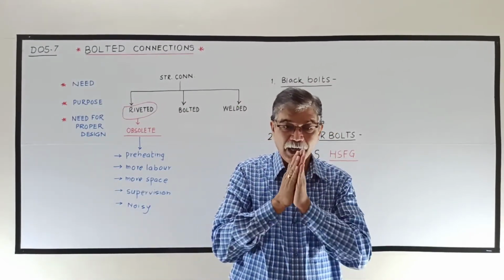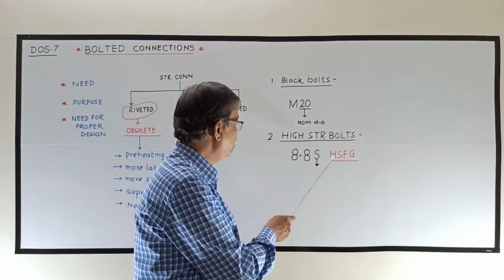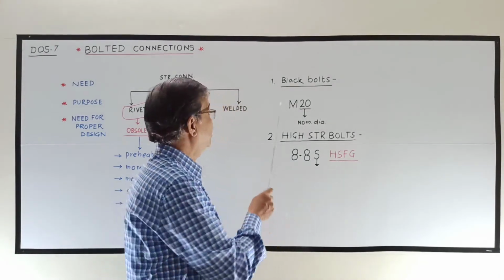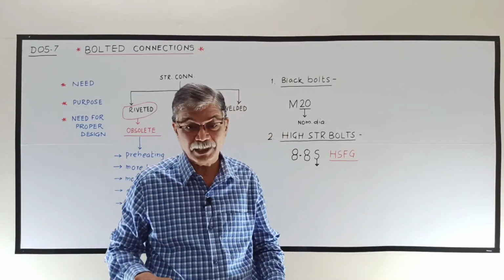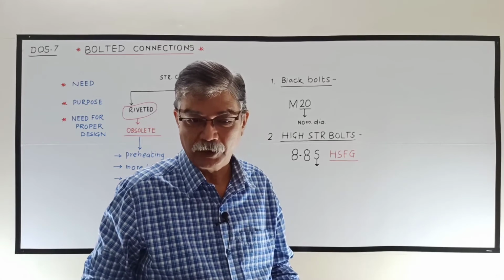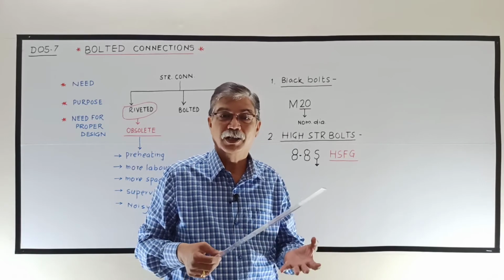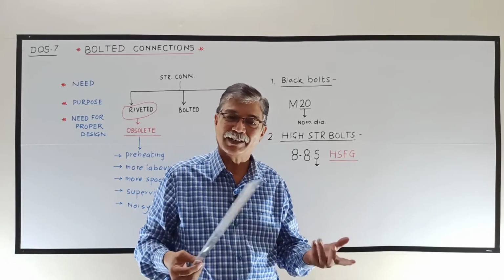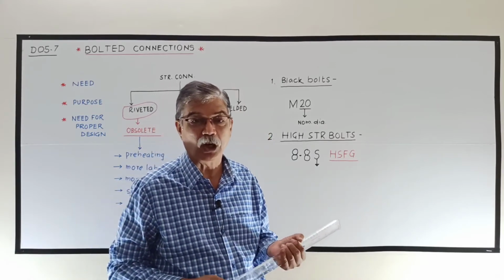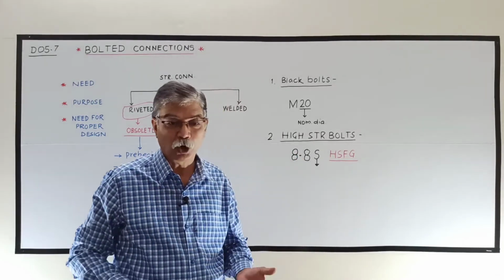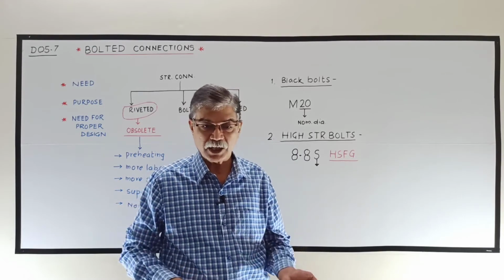Okay, now let us see the advantages of HSFG bolts. We already saw the advantages of black bolts. Now let us see what the advantages of HSFG bolts are. Definitely, you can use HSFG bolts for members subjected to impact, dynamic load, everything. For important structures also you can use them, which was not possible in the case of black bolts.